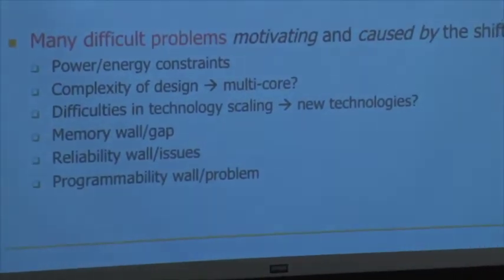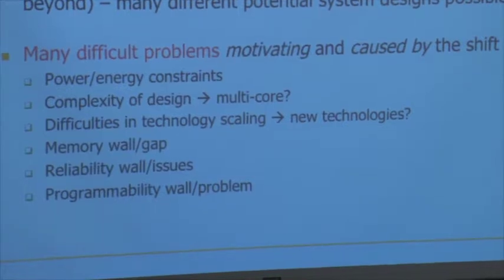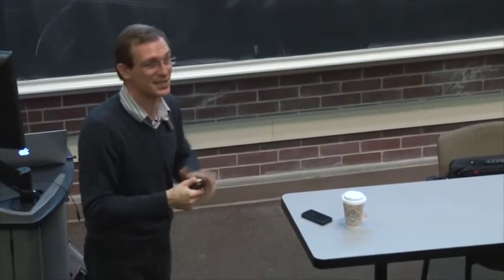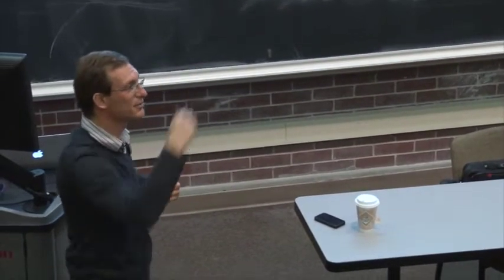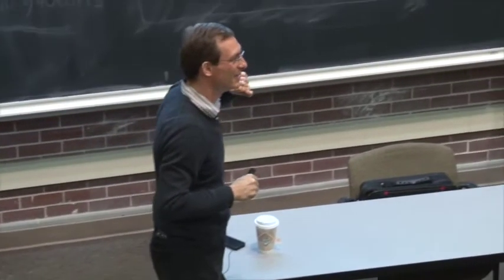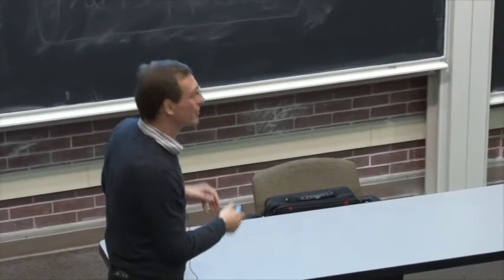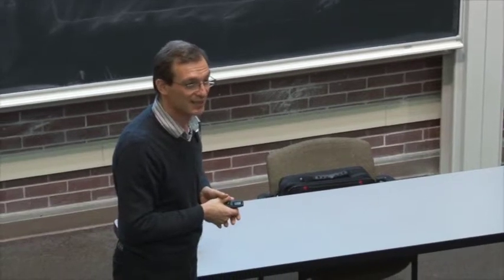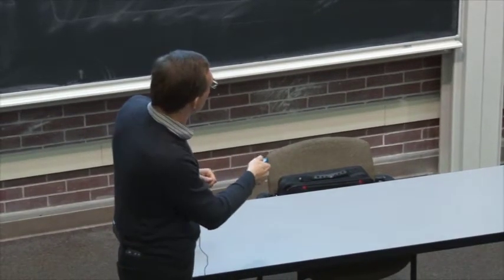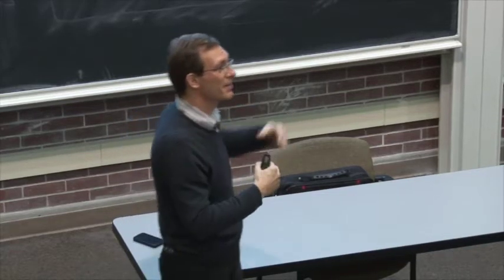How do we solve these problems through architectural techniques? It turns out this is a difficult problem to solve at the circuit level, because you do want to push it. You do want to cram more components, which means that you do want to scale the size down. And once you scale the size down, you need to find some other solution, maybe at the higher levels of the stack, at the architecture level. We will talk about some solutions. I don't want to go into this right now, but maybe I'll pose the question to you. Once you scale the size down, the refresh rates increase significantly. You need to refresh this cell much more often. Then the question is, how can you solve that problem at the architectural level?